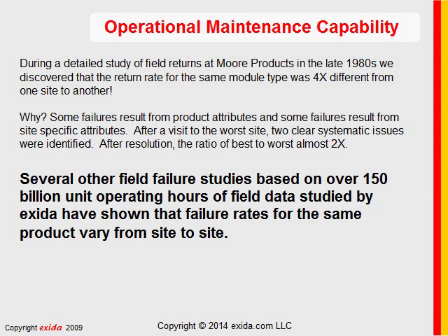Some of the failures were due to very systematic problems where untrained people were damaging the equipment during the proof test process, which can happen too. That's another reason why proof tests are not perfect.